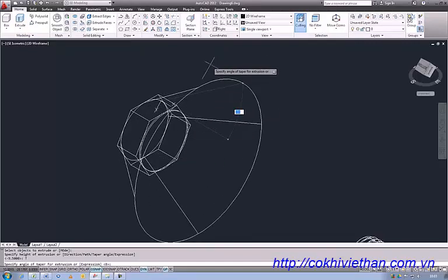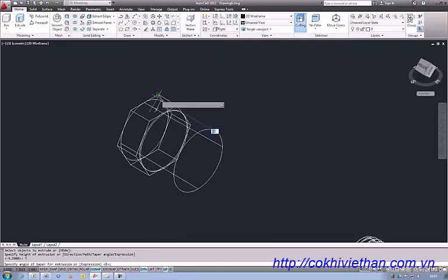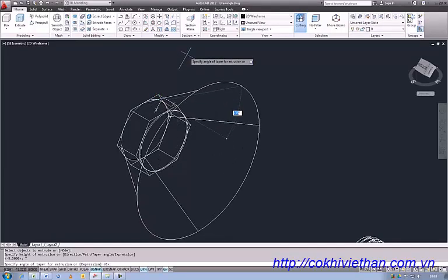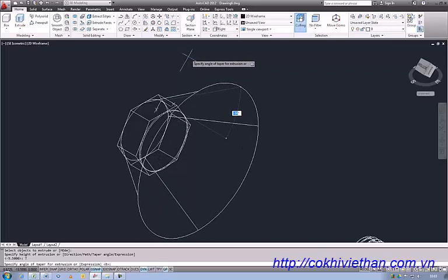So as we want to cut the corners of the bolt head off, we need a minus figure, and the angle is 30 degrees, so our dimension in AutoCAD will be minus 60 instead of 30. So hit enter,